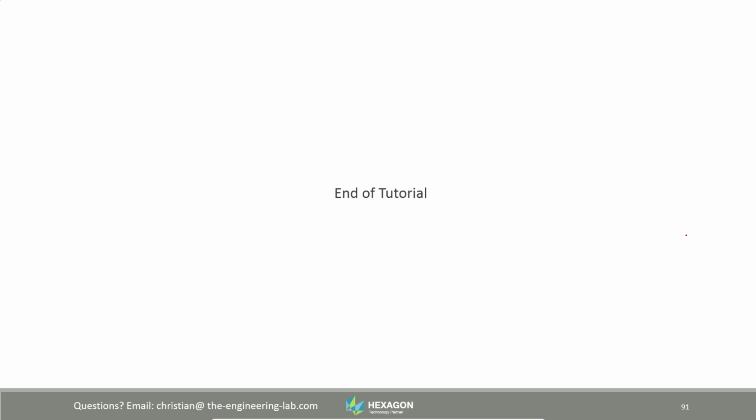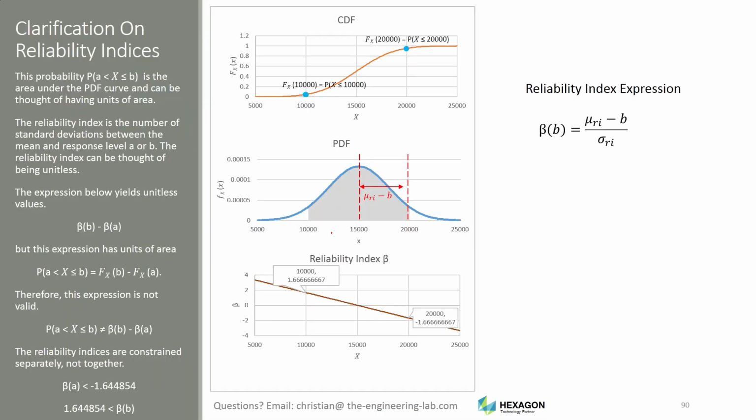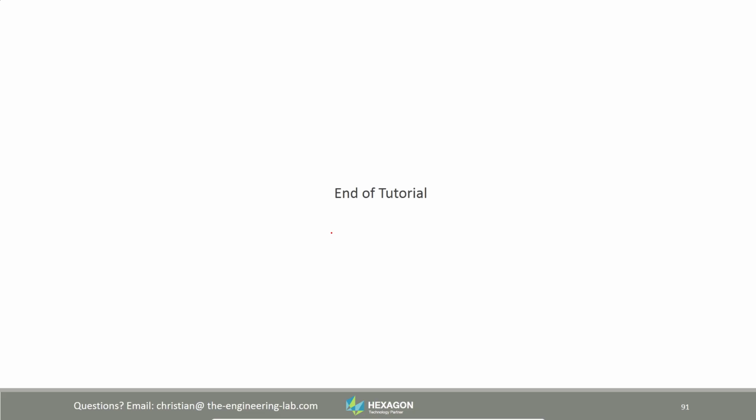We reduced the number of constraints. We determined the best starting location for the OUU. We configured the bulk data files to output the gradients. And then in part 2, we performed the OUU a different number of ways, all to reduce the number of Nastran runs that were needed. And then at the end, we made sure that our final probabilities of failure are satisfactory.